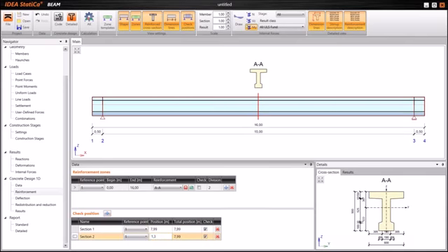Second section would be above the support. I am using the position 1.3 meters, which is at approximately the dimension d, which is, you see, 900 millimeters minus some concrete cover and centroid of the reinforcement. If we add 0.5, we approximately get 1.3, which is the section in which we should check it according to Eurocode.